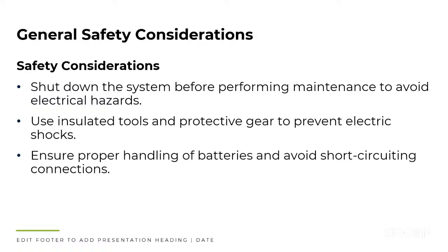They are not put on the floor. If they are put on the floor, then there should be a piece of timber raising up the battery, but also avoiding all small mistakes which will take us to short circuit connections.